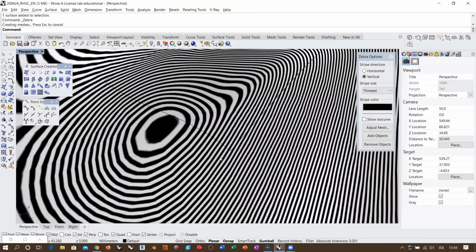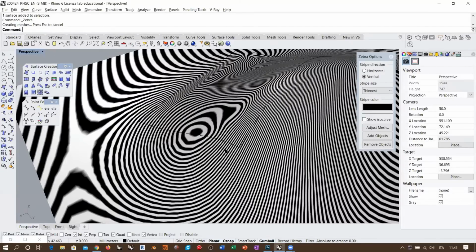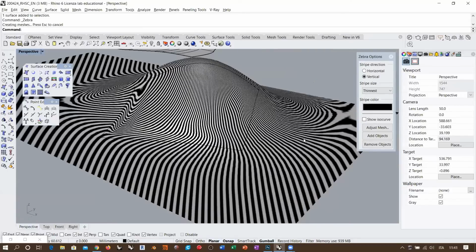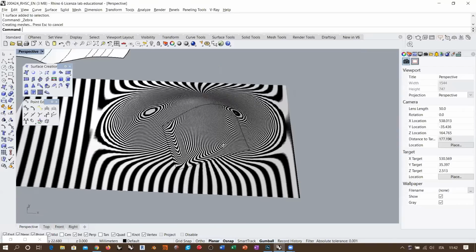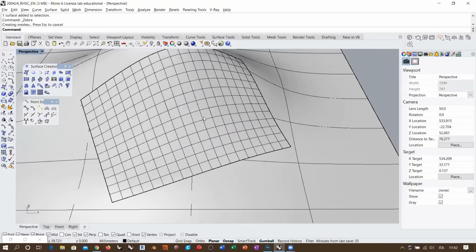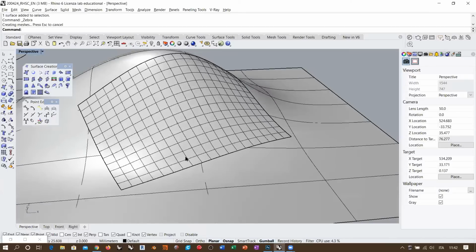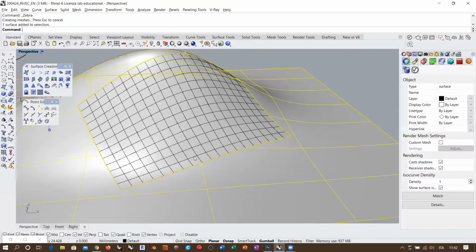But yeah, it's quite a good result we are getting right now, because we are starting from an extremely smooth surface that came from a deformable rectangular plane. Okay, but in general, the problem here is that what the command tries to do is, if you select curvature continuity along one edge of the network surface, the surface will be deformed in order to have the first 2 lines of control points properly set and adjusted in order to be continuous with the surface on the other side of the edge.